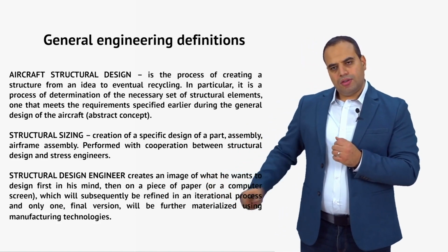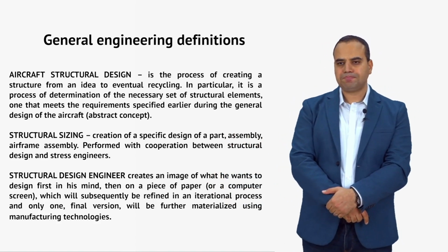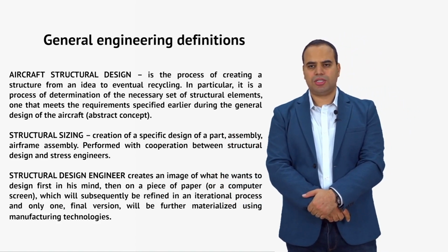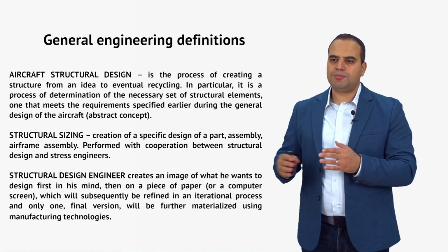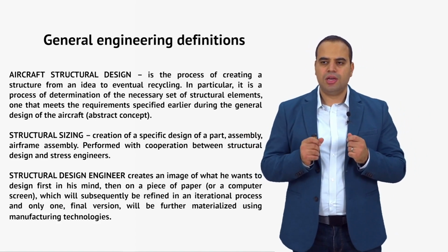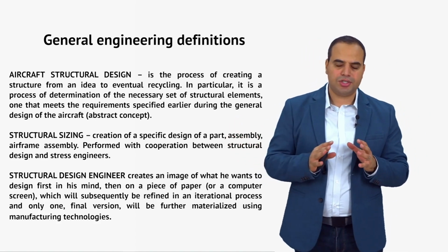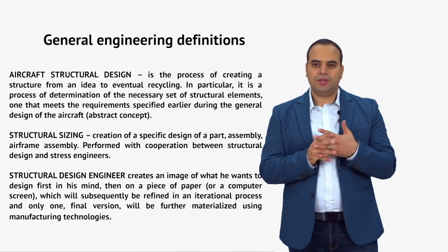Next, the next definition is called structural sizing. After we have an idea of which structural elements are going to be included in the airframe, it is the process of creation of a specific design of a part or airframe assembly, performed with cooperation between structural design and stress engineers. So this is a slightly more advanced level of designing the structure.